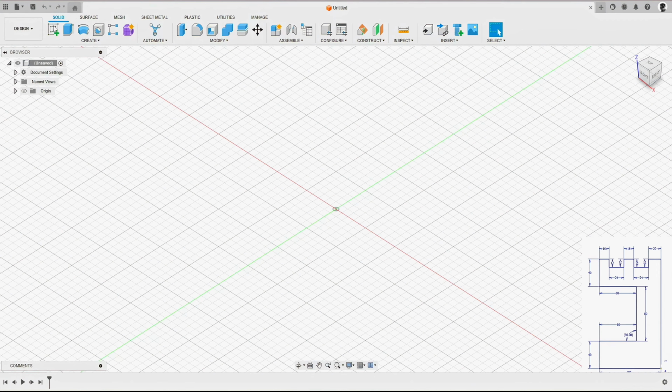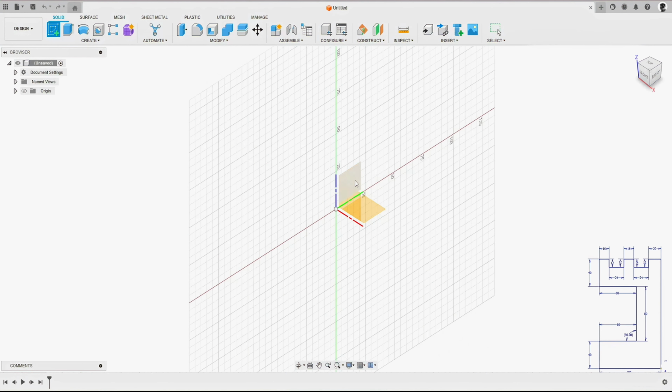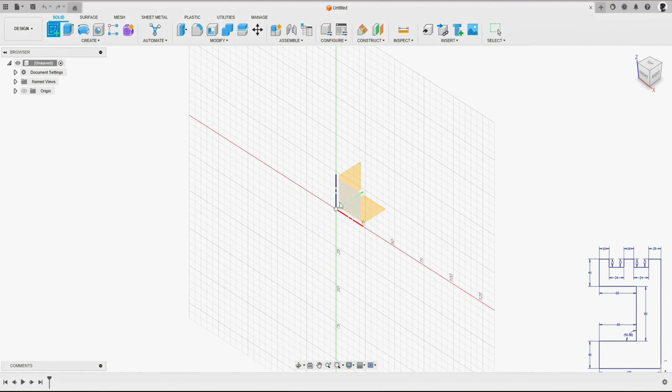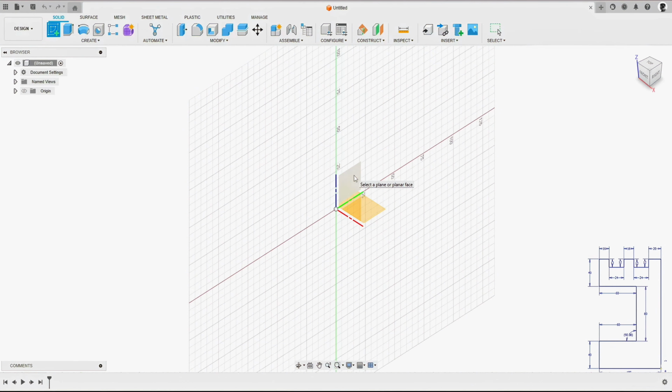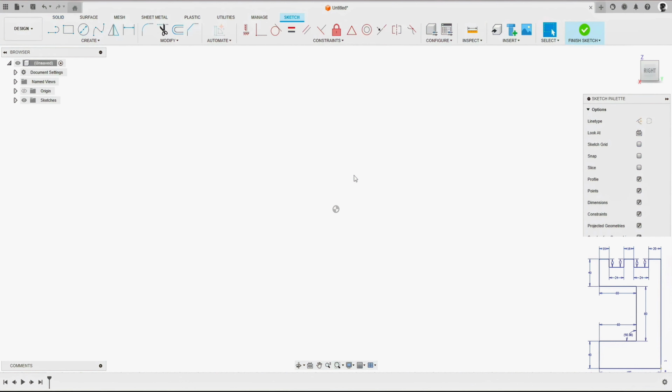So in today's lecture, let's revolve model a rotary part. This is the sketch profile that we'll be working with, and then once we complete that sketch, we'll proceed to revolve this around one of the default axes. So jumping into Fusion, let's go under Create Sketch. For this, we could choose any of the default planes, and then we'll select the according axis for us to revolve that around. In this case, I'm going to go with the YZ plane.